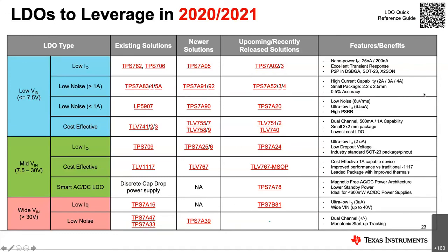The second question is why the critical frequency range is from 1 kilohertz to 1 megahertz. That critical frequency is actually more just for image sensors. Ideally, we have 100 kilohertz as the sweet spot for the frequency, because if you have sufficient PSRR, then it'll be able to reject all the upstream noise. So 100K is typically where we would have that metric, but in general, since there's a wide range of image sensors in the market, 1 kilohertz to 1 megahertz is the range.